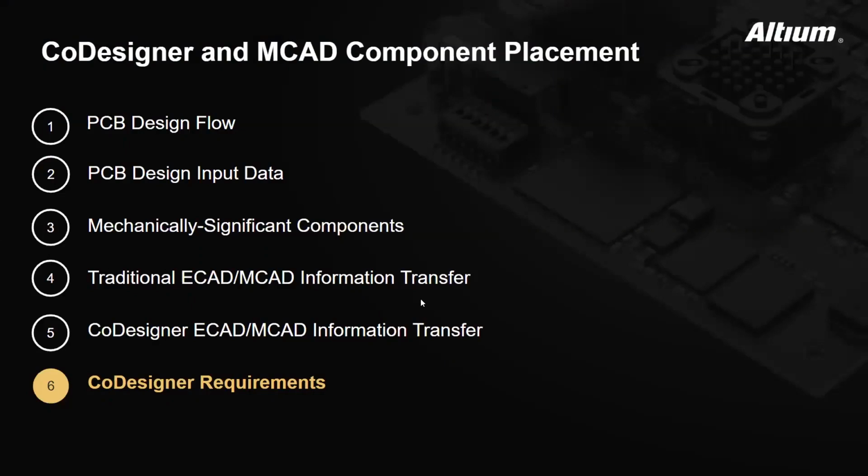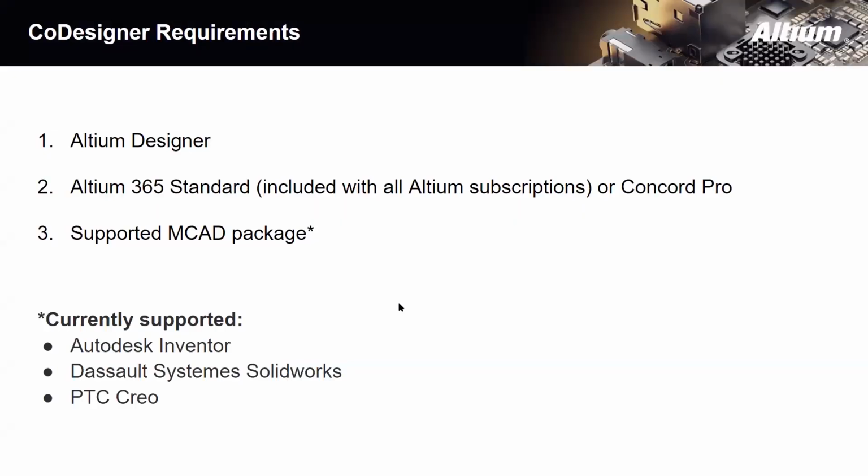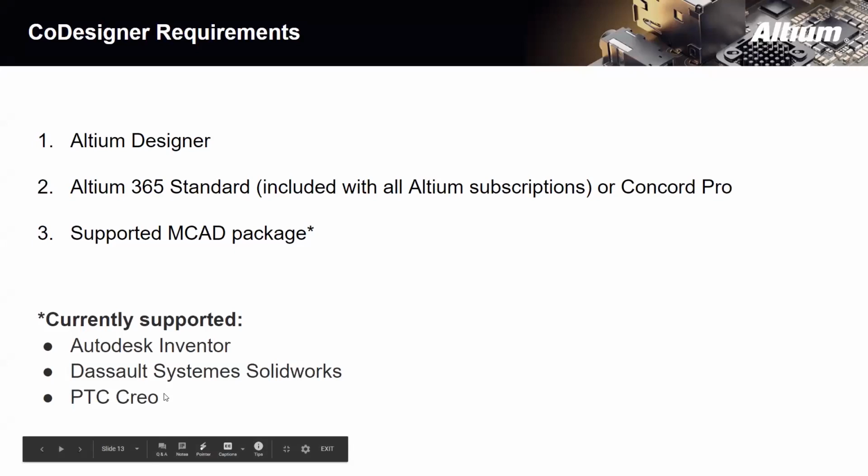So what do you need to be able to use CoDesigner? Well, Altium Designer, obviously, and an Altium 365 standard subscription, which is included with all Altium subscriptions, or Concord Pro. And you need a supported MCAD package. The currently supported packages are Inventor, SolidWorks, and Creo.